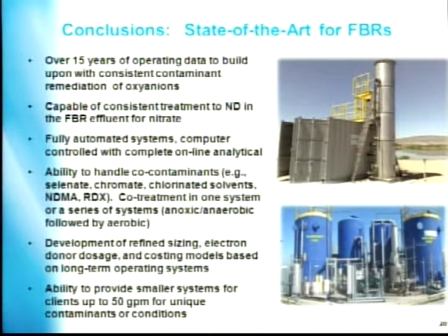And for the small communities, though, we can build these very small systems, and the one up top that you see is the city of Barstow in the photo there, and that's also a 3-foot diameter reactor with a small Connex box, and that's the FBR technology right there that could be used for 50 gallons per minute. Depending on the nitrate loads, you could actually maybe get even a smaller column. You still have to go to filtration and disinfection, though, and that's critical to realize.